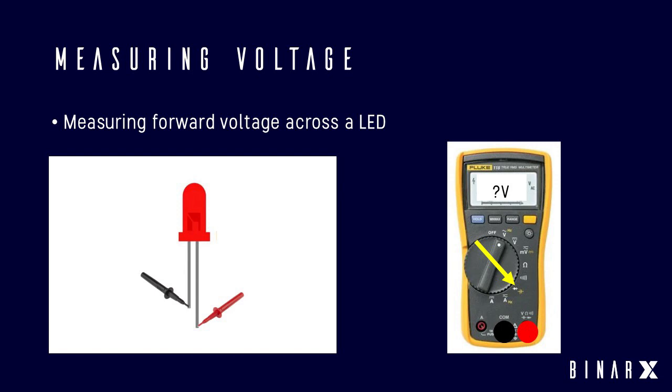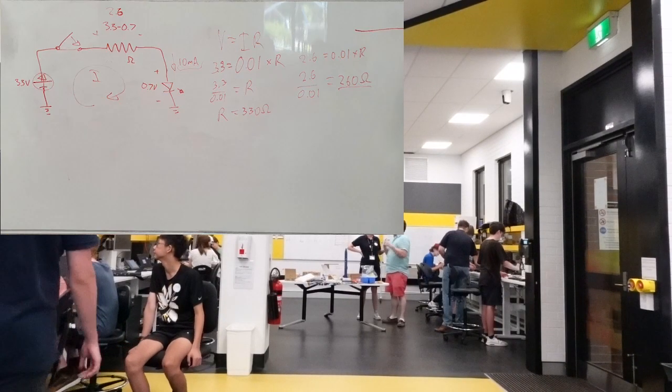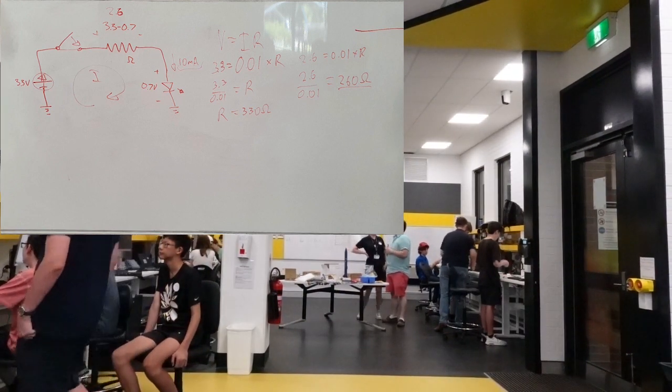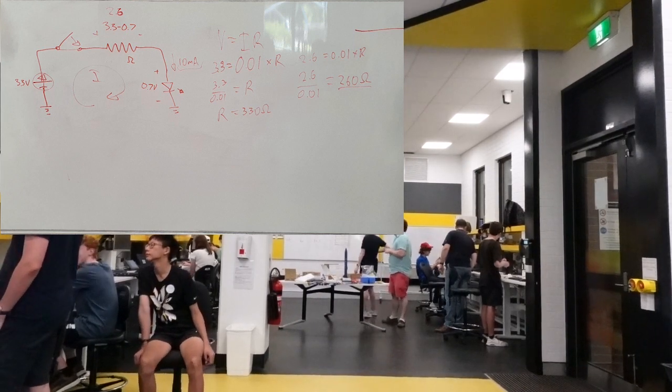All right, so everyone's got an LED, you've written down the number. What I want you to do is go to your multimeter and have a look. There's a button that looks like the symbol for the LED, just without the little arrows coming out of it. Everyone see that? I want you to press it. If you want to grab the little legs of it and spread it apart a little bit, and then just hold the probes. You can touch it.